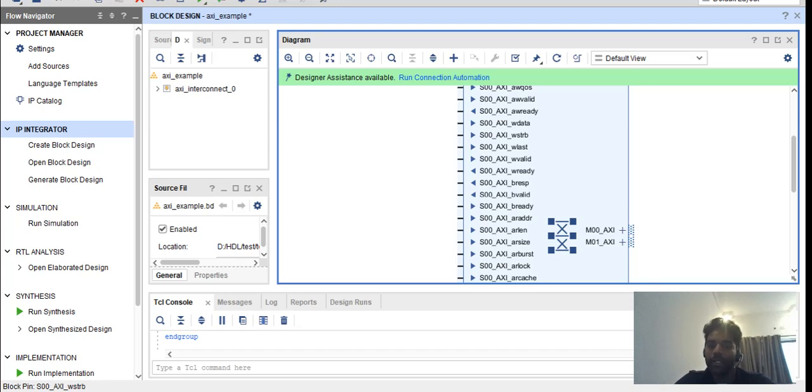So this will be taken care of by the master, because the master already has the settings, like the configurations, like how many bursts are to be sent for each address. So once the address is initialized, the write data channel will be ready for you to send the data. So once you initiate your valid, this valid has to stay valid till the burst ends. So based on the burst type, you can keep this valid active.